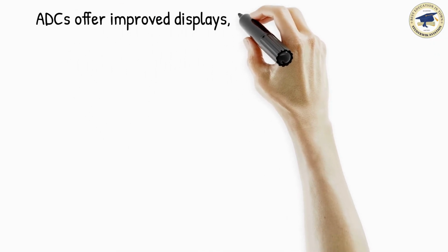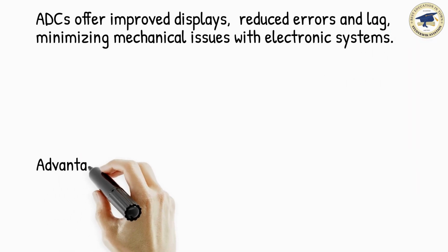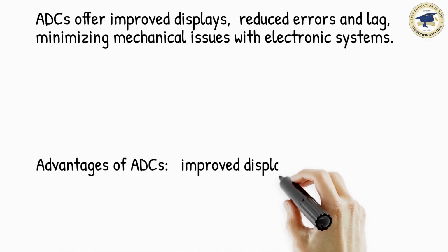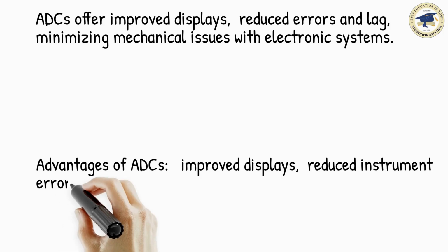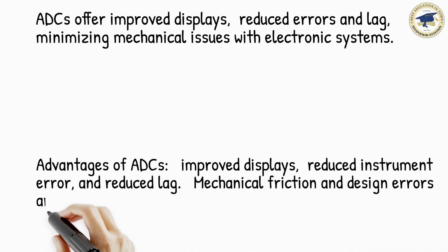Advantages of ADCs: improved displays, reduced instrument error, and reduced lag. Mechanical friction and design errors are minimized with electronic systems. Configuration modules correct for position error and K-factor.